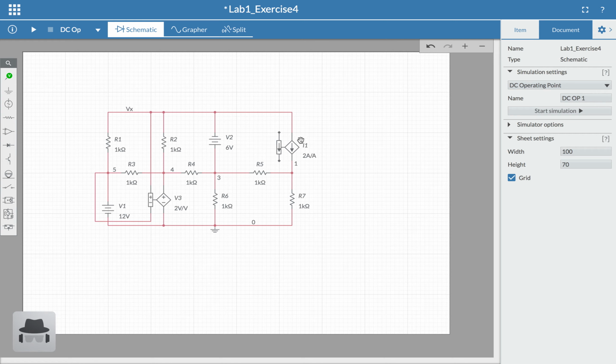All right. So we're going to do the same thing with the current. Now current is not like voltage. When you measure current, you measure what's going through some wire. So we're going to have to break our circuit. Whenever you're measuring current in this class, make sure that you break your circuit. It's probably one of the hardest things that students struggle with in here. And so what it's saying is the current going through this resistor here is going to be what this thing generates, but twice as much, because we set the gain to 2.